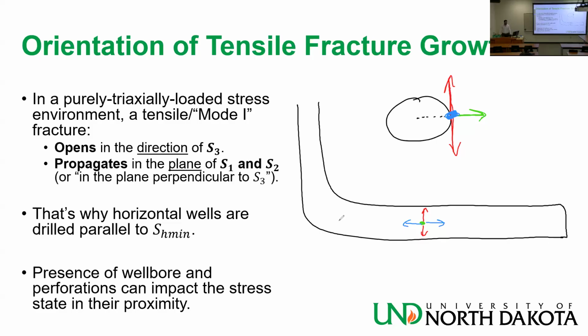And again, if you want debonding, you have to go against sigma RR. Imagine this is like this, and I want to debond the cement from the wall of the well. I want to push it out, so I'm working with sigma RR. I'm pushing it out, pushing it out. It's a tensile failure again. Very nice.